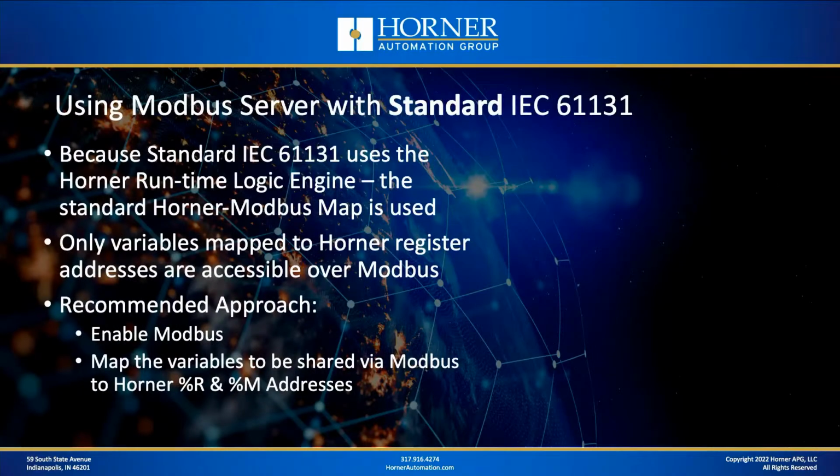Now let's start with the details on how to implement Modbus server with standard IEC. Remember, it uses the standard runtime engine, so therefore it can use standard Horner to Modbus memory mapping. So the approach we're going to take here is we're going to develop our application and test it, make sure everything's working the way we want. We're going to make a list, kind of on paper, of the variables that we want to share over Modbus and create a Modbus map that we want to be able to publish to our customers.